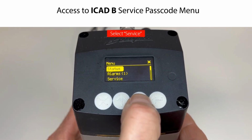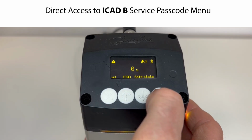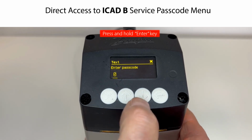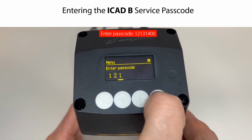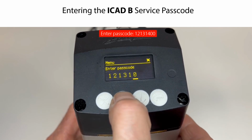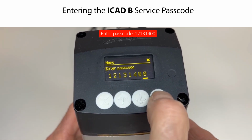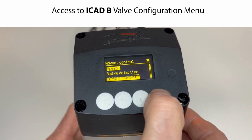Therefore, press enter and scroll down to service. Then press enter. Alternatively, from the main screen, press and hold the enter key to go directly to the passcode menu. Enter the 8-digit passcode, which from the factory is 12131400. Select each number of the code by using the arrow up key and pressing the enter key between each number to confirm it. After entering the passcode, then scroll down to Advanced Control.